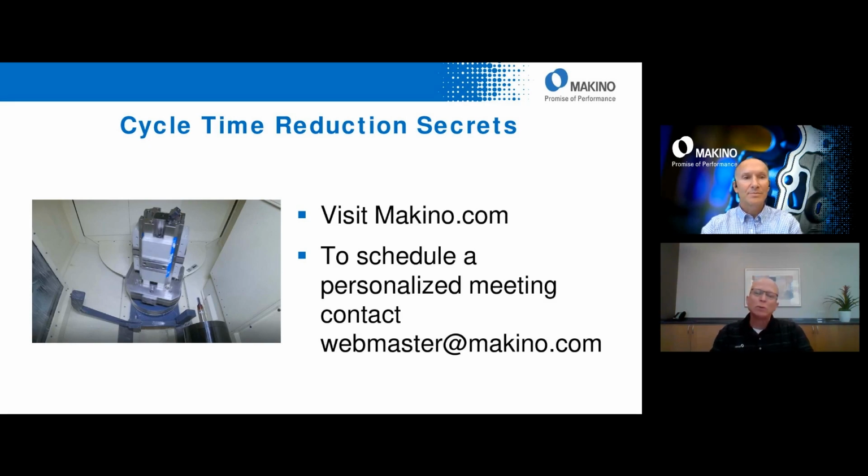So Mike, yes, there's one more thing that I was reminded of yesterday talking to a colleague here: there's another set of powerful M codes. It's kind of a common theme. We're going to dig more into some of these special M codes in our next part. But one set of M codes I'd like to mention today, it's not necessarily a cycle time reduction, but more of a reduction of your unplanned downtime. And that is M36. What that M code does is a prior tool check.